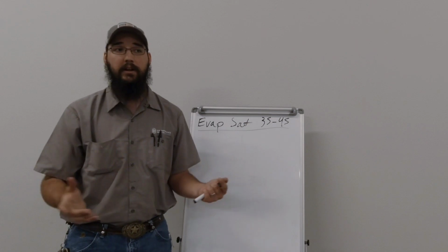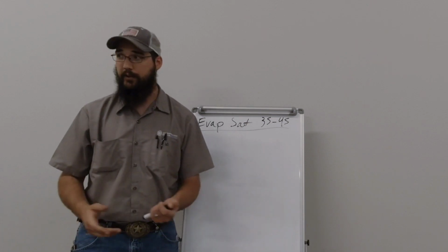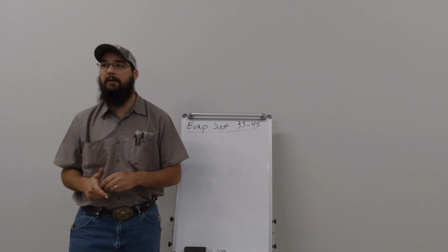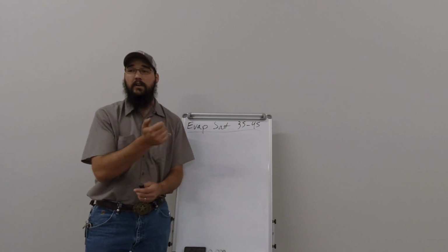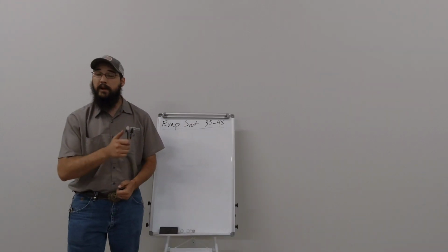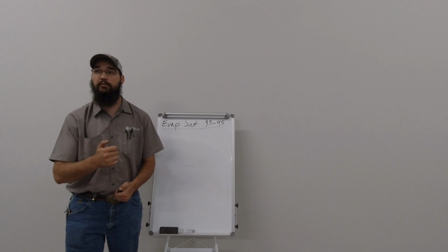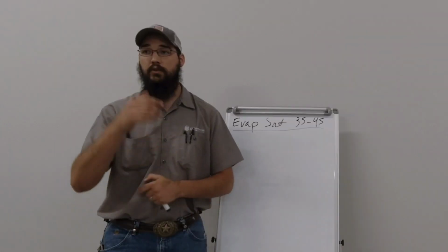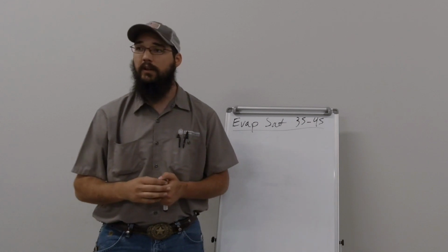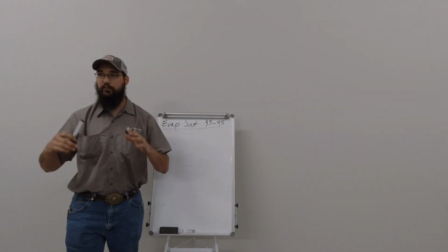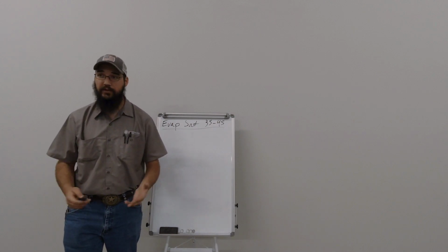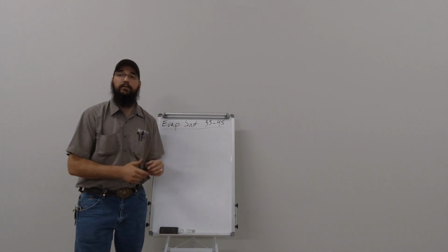And I highly recommend the Danfoss refrigerant slider. The Danfoss refrigerant slider is my most recommended app for that. And it has a toggle button on there to switch between bubble or dew. You have to make sure, depending on which side of the system you're reading, you're on the right setting. Because if you do some tests, I think some of them are up to 10 degrees difference in normal operating range. It's really critical we pay attention to those things. Again, we start talking efficiency. All of this is built into efficiency.